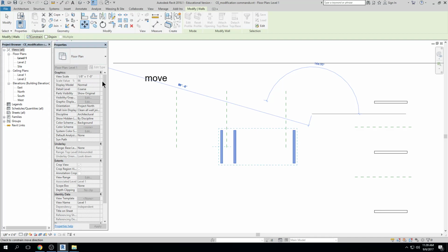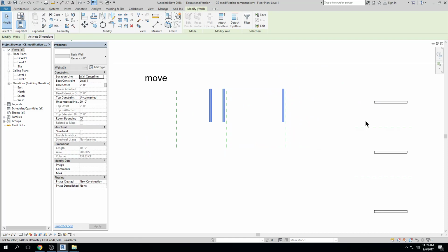If I constrain, a lot of times I won't be allowed to move in one direction or the other. So sometimes it's horizontal, in this case probably because my cursor was moving this direction, but other times if it's an object connected to something, it will only move vertical, right? So it kind of depends on the object. I also have disjoin, which means, hey, don't constrain, just let me move wherever I want to go. So that is essentially like having ortho on and then turning it off.